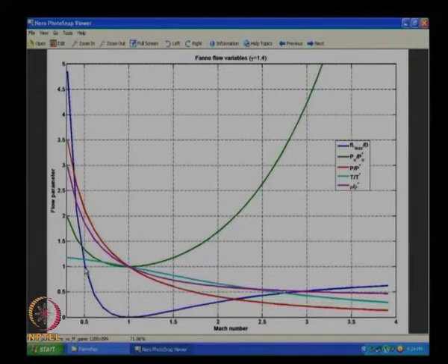So what we are finding is, if my Mach number is, let us say, 0.5, it has some particular f L max by D, and if I fix my f and the D to be the same for two different comparisons, my L max is some particular value for this. If I go to some Mach number closer, I find that the L max has become half. That is, in half that length, it is going to reach M equal to 1. Mach number was changed by so much.